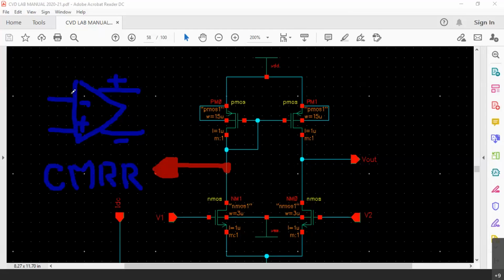So, if noise occurs here, noise is going to affect both the inputs. Now, inputs are differential, outputs are also differential, which means even if the common mode noise is amplified, at the output the noise will still be reduced because the output is also taken as differential. That is how a differential input, differential output amplifier will have a much larger common mode rejection ratio.